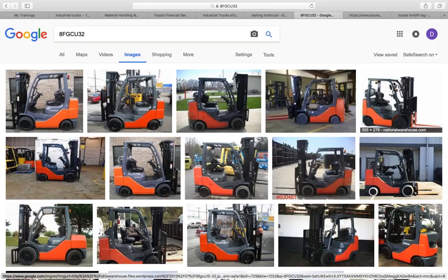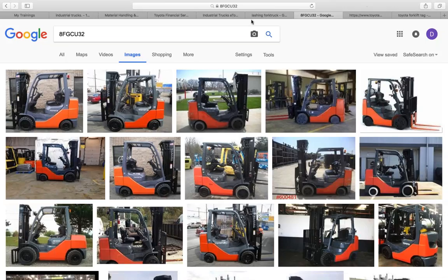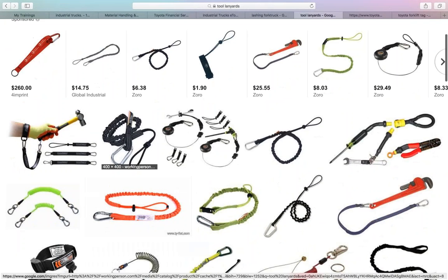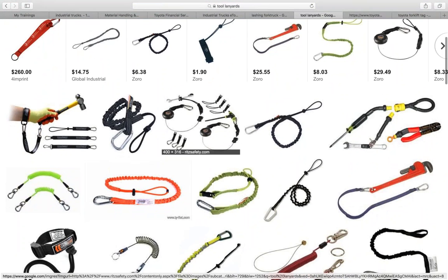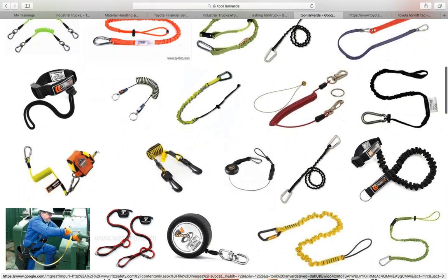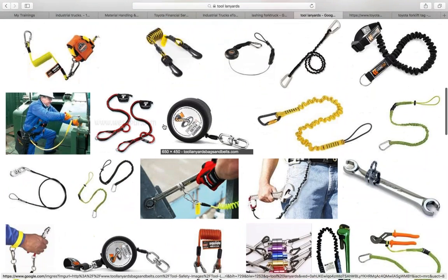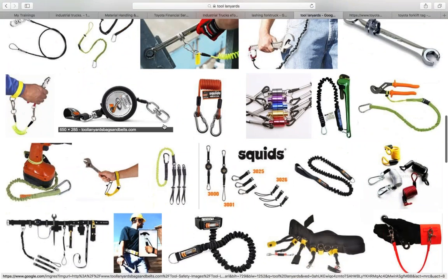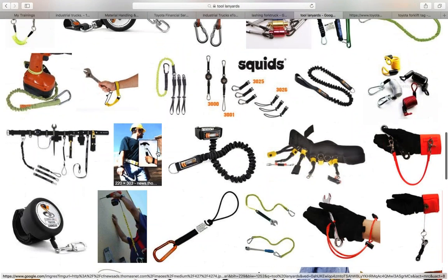We're also going to use tool holders, tool lanyards, or ropes. For anybody who's not familiar, let me see if I can pull up a tool lanyard for you. It's what I'm talking about, like whips and tools like this. Have any of you seen these yet on your work sites? Like holding cordless drills. A lot of times you'll see some cordless drills have a hole in the backside, right? Okay, good. So, different types of tool lanyards.